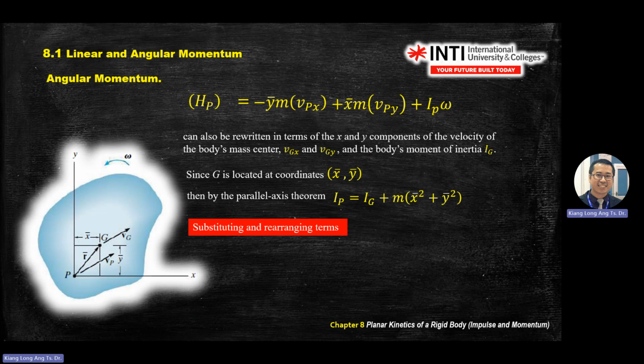Sometimes the question will give you hints that you need to use this, by mentioning the parallel axis theorem. This one you learned in statics. But in this module, you don't need to calculate the centroid and everything. In this module, you only need to refer to the appendix, the table form.